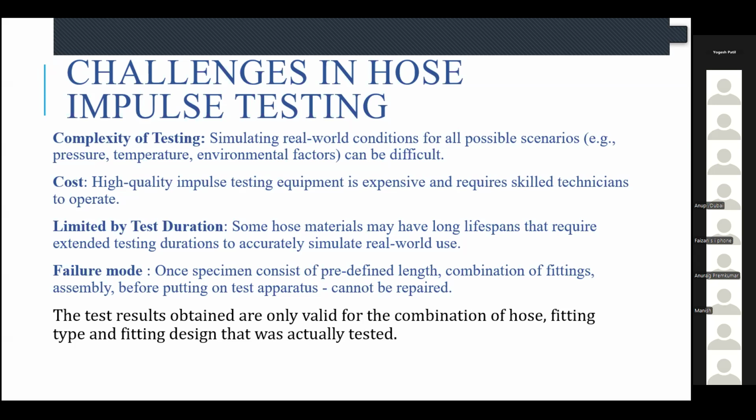Before putting the hoses into impulsation, it is mandatory that all this testing is done, and even the standard forces us to do those tests. At least the bare minimum of those tests needs to be carried out before putting into the impulsation chamber, because impulsation is a long-duration and complex test. So one needs to take care that all tests suggested by the standard are done, and then we put it in the impulsation, so failure mode chances are minimal.